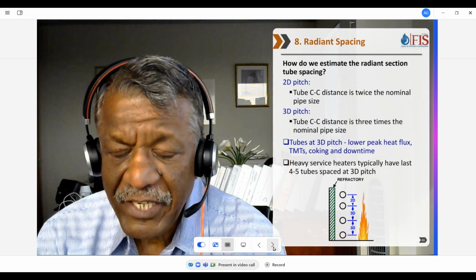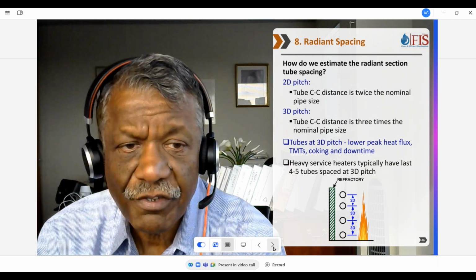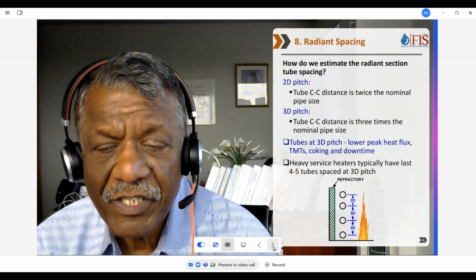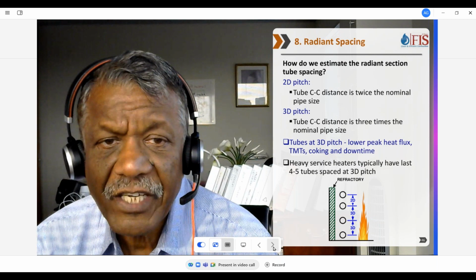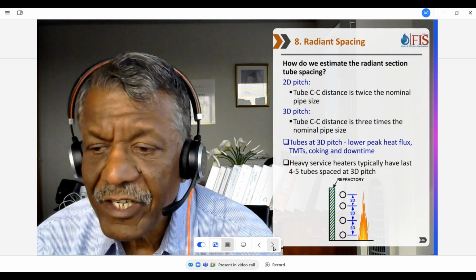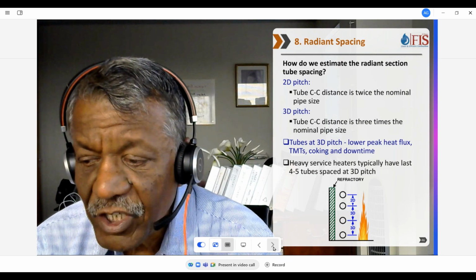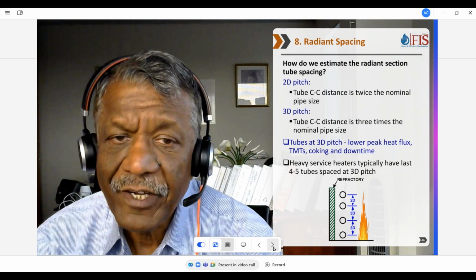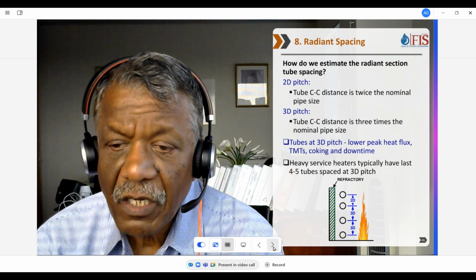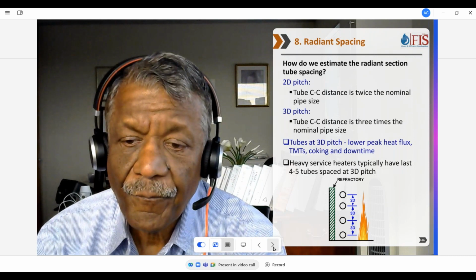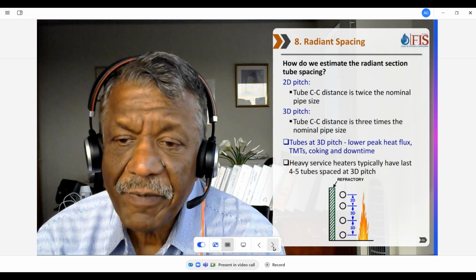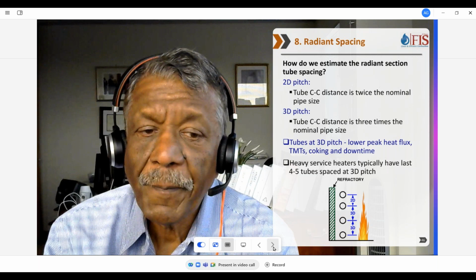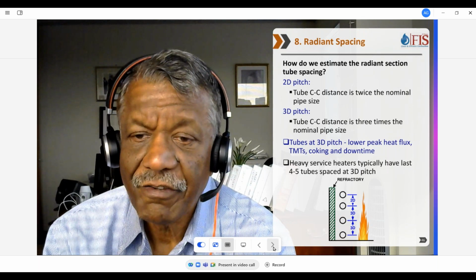We have a few minutes, so I had received several questions from our participants. So I will take some of these questions. Already we have taken this one. So what is the radiant tube spacing? Radiant tube spacing, in most of the heaters, will be at 2 diameters. Lobo and Evans did experiments, and there are other people also who did experiments, and they found that 2 diameter spacing is the optimum spacing for most of the heaters.